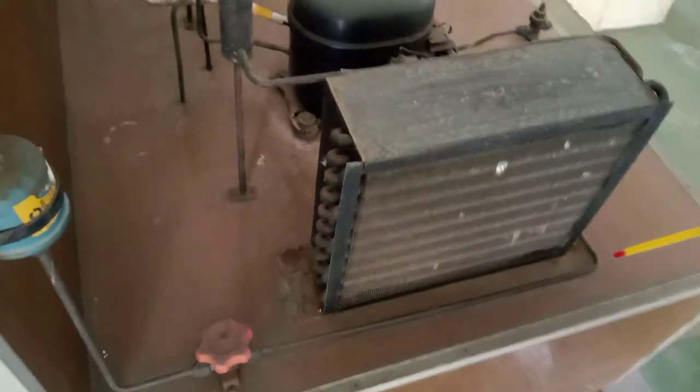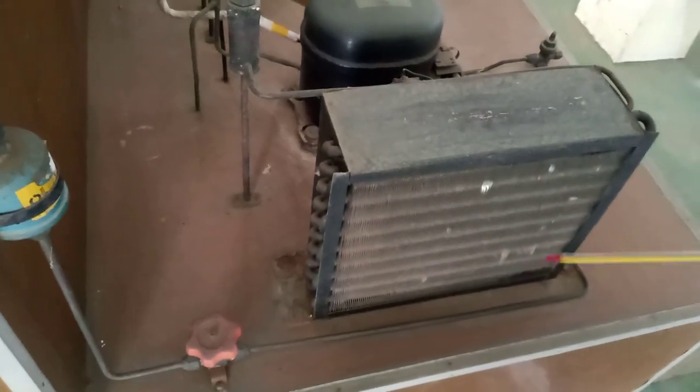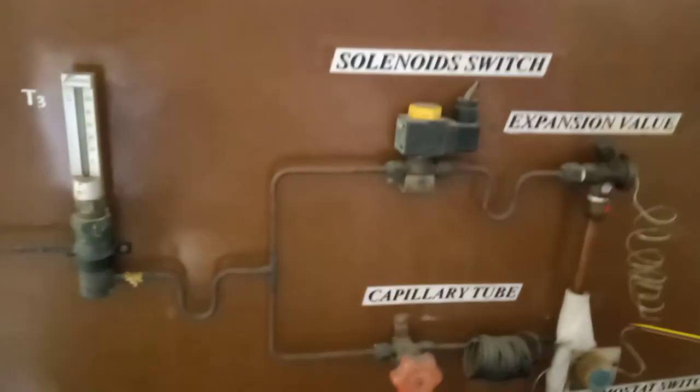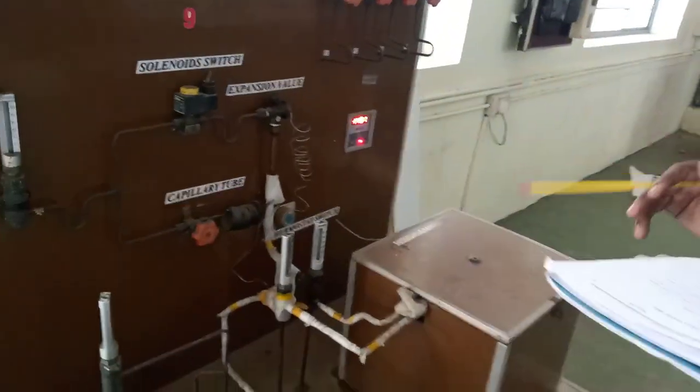You can see how this temperature is increased. It's 50 degrees Celsius. Then it enters the condenser, where it loses its latent heat without changing its temperature and pressure. But in the actual case, there will be a decrease in temperature. Here you can see the temperature is about 39 degrees Celsius. Then it enters the expansion valve. After the expansion, the pressure reduces and the temperature also reduces, so the temperature will be very low. This is how refrigeration testing works.